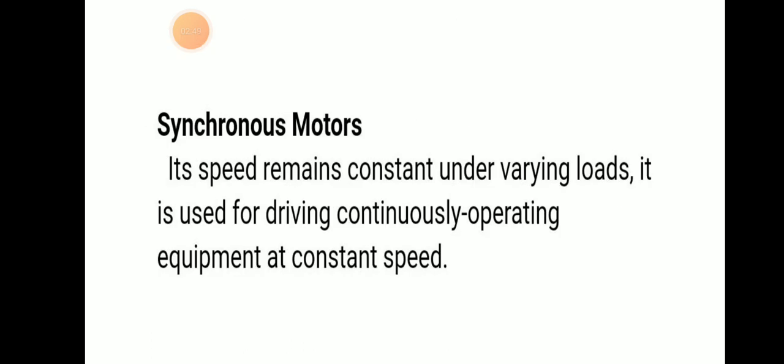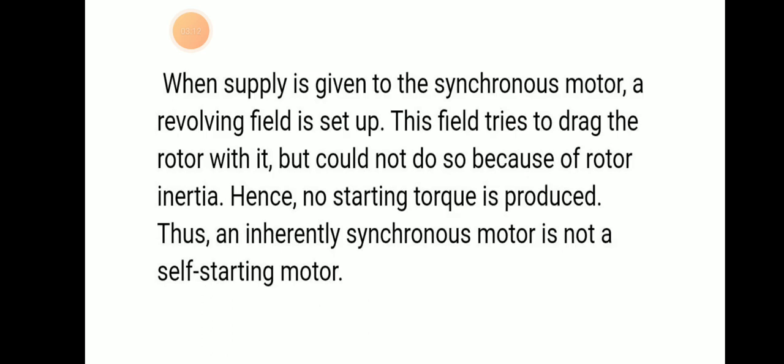And another one is the synchronous motor. The synchronous motor is, we can say, the exact opposite of the asynchronous motor, meaning its speed remains constant under varying load. With varying loads also their speed remains constant. So it is used for driving continuously operating purposes with constant speed. If you want to pump water or any fluid with constant speed, then we can use a synchronous motor.